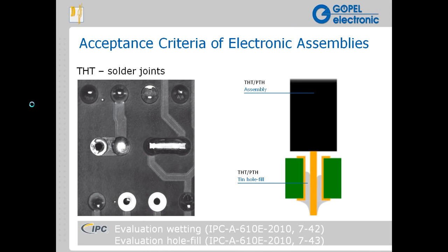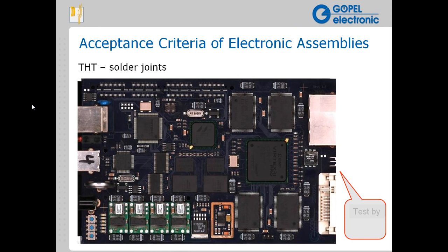However, with 2D X-ray, we can actually see the density of the solder joint more clearly. And with 3D X-ray, we can actually see through the entire barrel fill element of the hole. So we can characterize with 3D AXI the actual fill of the hole itself in terms of the percentage. To look at this a little bit more closely, let's look at this particular illustration.